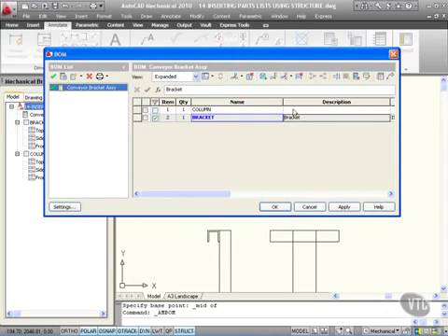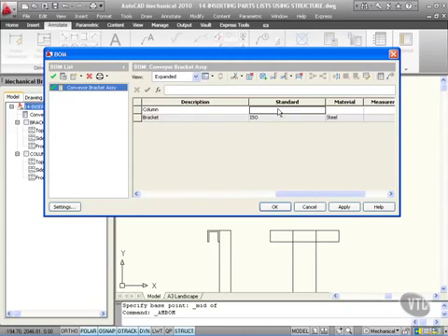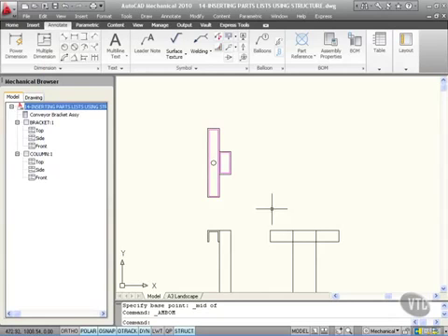Now you've got a description there. I'll put a description in here as well. Just column like that and enter. Standard there. We want ISO. So let's put all this in, and also material there. It's going to be steel. So that's all in there. So I'll apply all of that and OK that. So I've now got a bill of materials created from my mechanical browser instead.